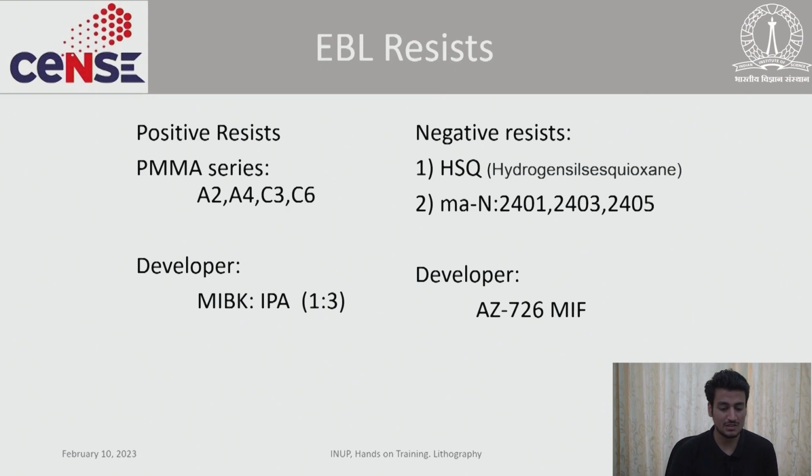Now these are the EBL resists which we are using. We have the PMMA series, and for negative resist we have the MAN series and HSQ, and as developers we are using MIBK IPA and EZ MIF 726.